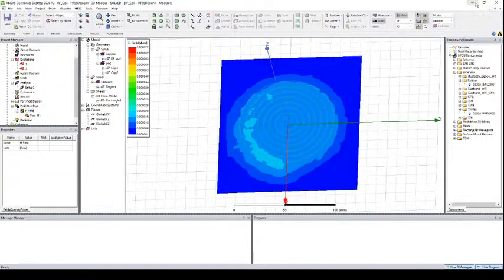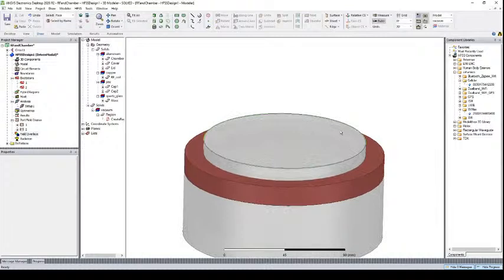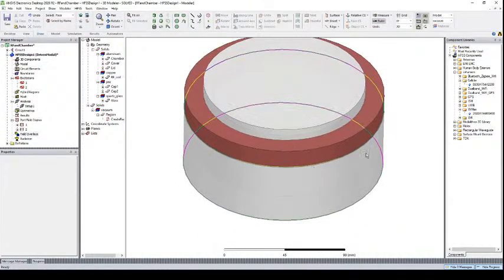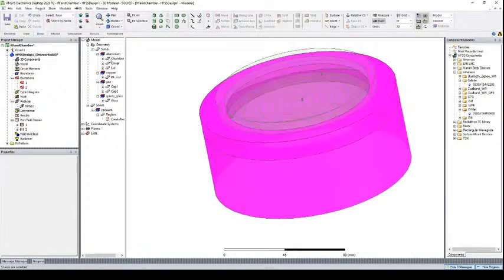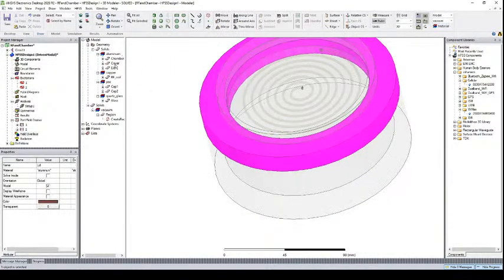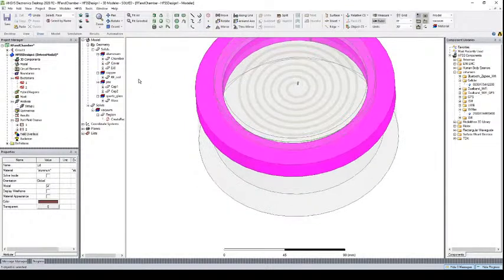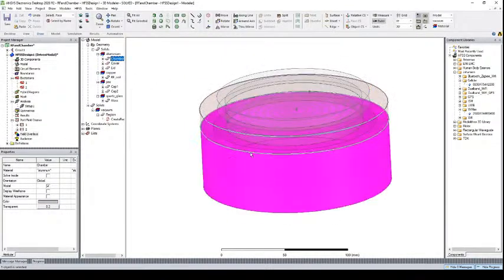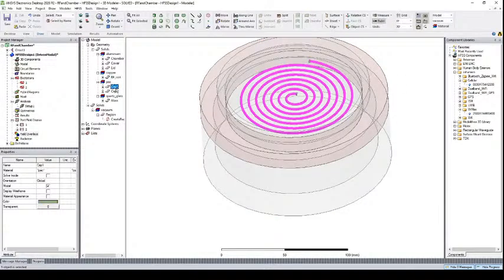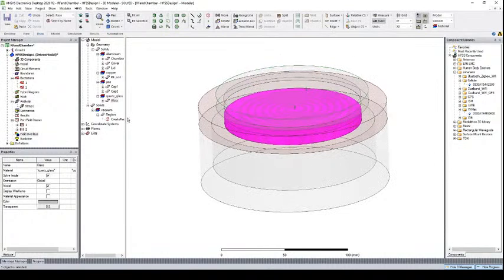Okay. So next we are going to look at the chamber. This is the chamber that you just looked at here. We have the aluminum for the lid, and we have the cover aluminum. We have the chamber and RF coil. We have two caps, and we have the quartz glass. For the material properties, these are all included in the ANSYS material library. You can find most of the standard materials inside the ANSYS material library.